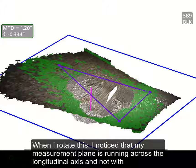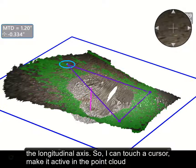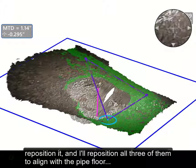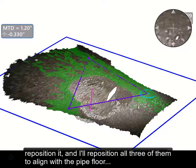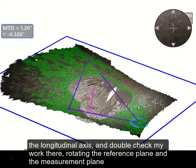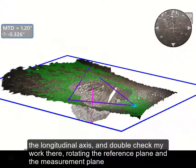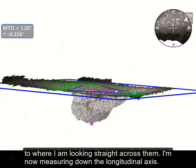When I rotate this, I notice that my measurement plane is running across the longitudinal axis and not with the longitudinal axis, so I can touch a cursor, make it active in the point cloud, reposition it, and I'll reposition all three of them to align with the pipe floor, the longitudinal axis, and double check my work there, rotating the reference plane and the measurement plane to where I'm looking straight across them.